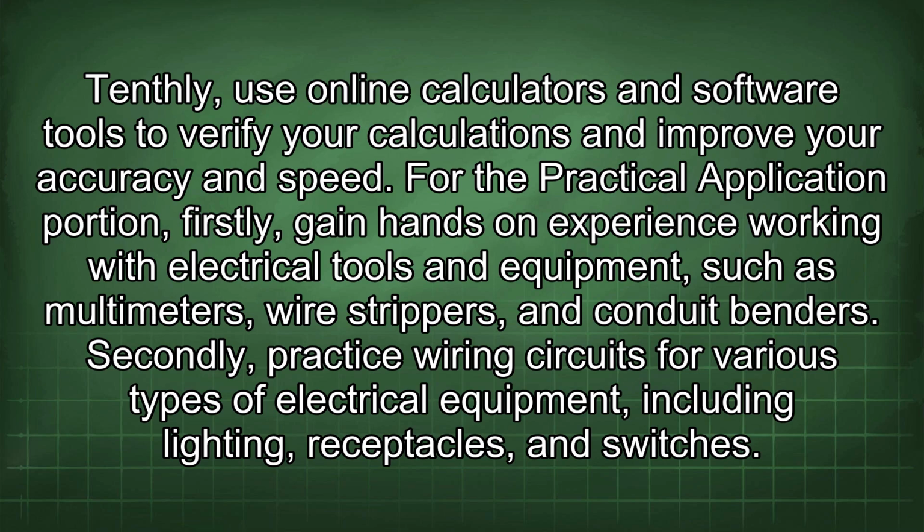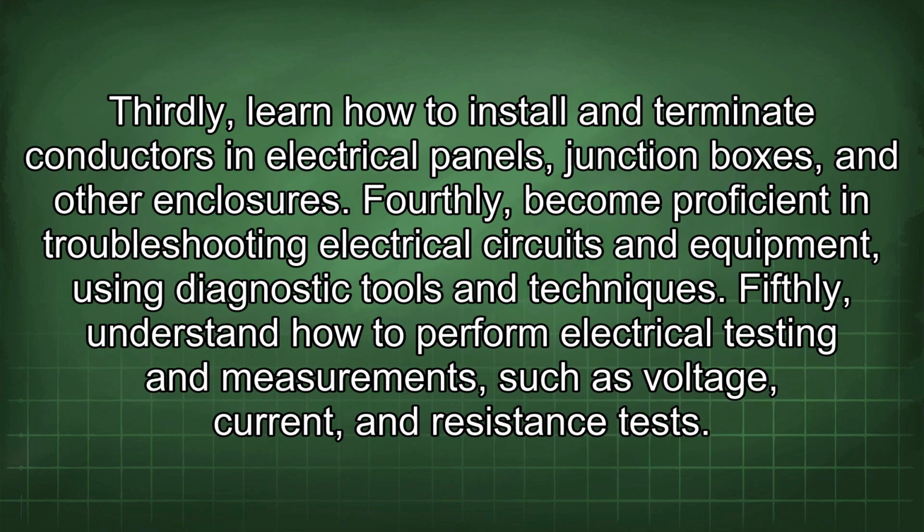For the practical application portion, firstly, gain hands-on experience working with electrical tools and equipment, such as multimeters, wire strippers, and conduit benders. Secondly, practice wiring circuits for various types of electrical equipment, including lighting, receptacles, and switches. Thirdly, learn how to install and terminate conductors in electrical panels, junction boxes, and other enclosures.